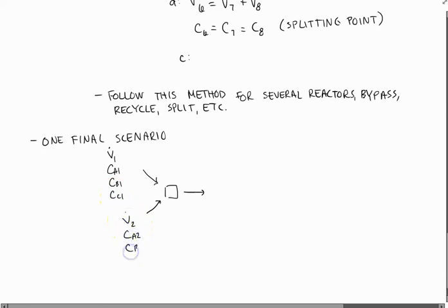I've got A, B, and C denoted by subscript, and I've also included a subscript for the number that I've given the stream. And what you can do here is you can see this mixing point has four potential mass balance equations, one for the carrier fluid and one for A, B, and C. So I'll go ahead and write those here.